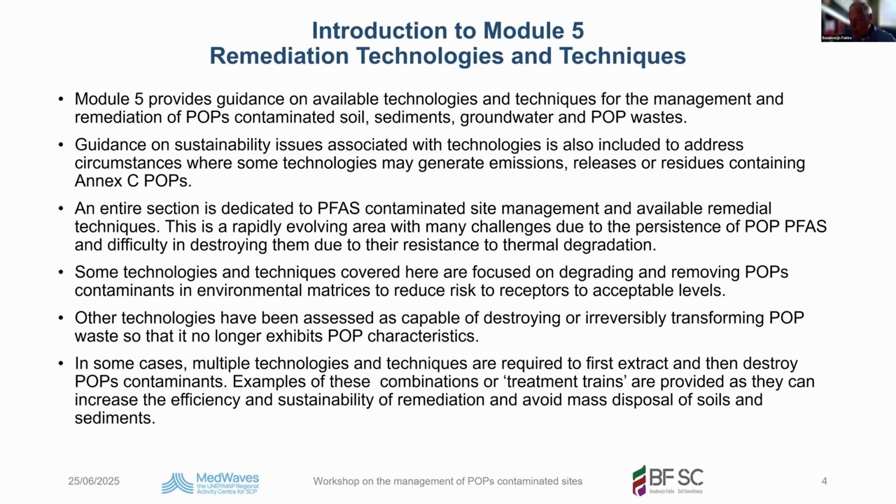Other technologies have been assessed as capable of destroying irreversibly, transforming POPs waste so that it no longer exhibits POPs characteristics. So that's the difference. We discussed technology that reduces the levels, and we discussed technology that completely removes or destroys. In some cases, multiple technologies and techniques are required to first extract and then destroy POPs contaminants. Examples of these combinations or treatment trains are provided as they increase the efficiency and sustainability of remediation and avoid mass disposal of soil sediments.